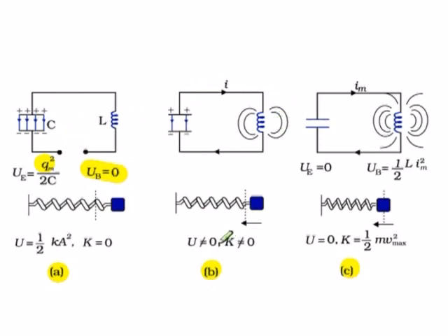Therefore, U, the potential energy, the electrical energy at the capacitor, because of some charge that is remaining there, is not equal to 0, but it is definitely less than U max at the capacitor. K, that is the kinetic energy, the magnetic energy at the inductor, is also not equal to 0, but it is less than the K max that will be at the next stage.